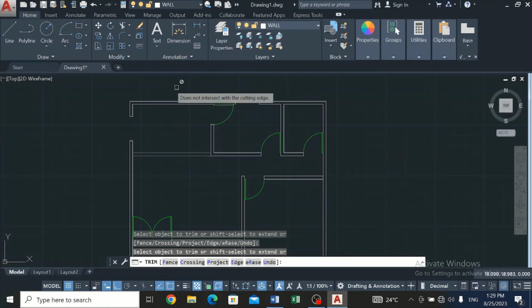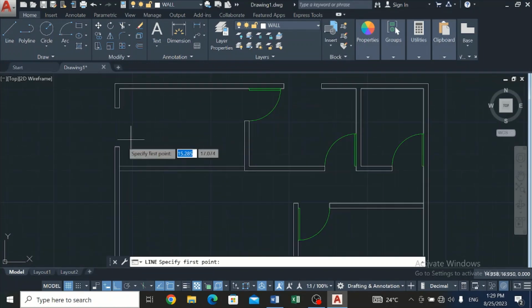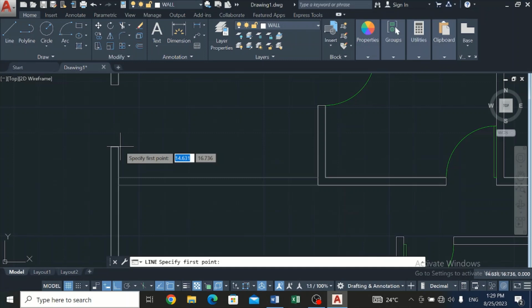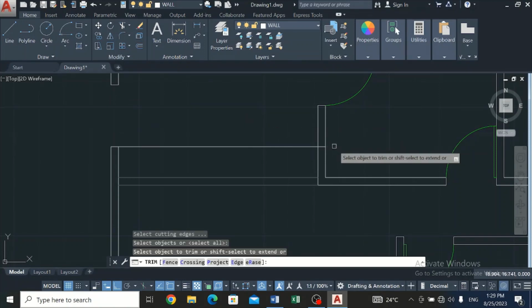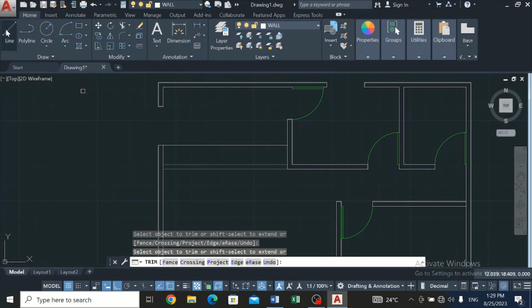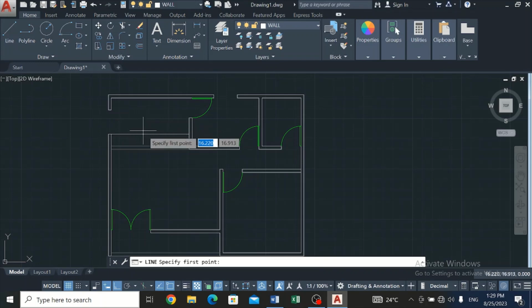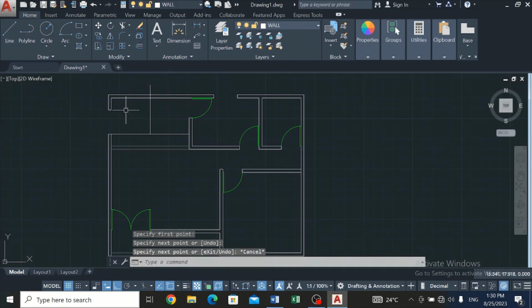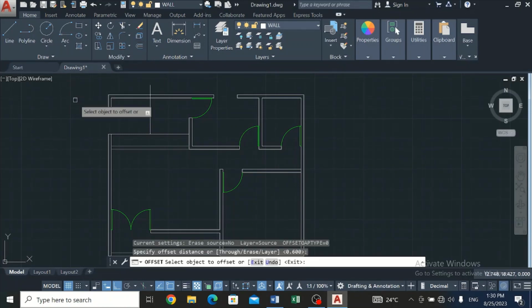I need to create an opening over here, so I'll create a line, drag, hit over here using my trim key, my trim tool. I right click, click on it and this. Now I pick out this line, I click on the line tool again and I move across to get to the midpoint. I drag, I hit the escape button. Now what I need to do is to use the offset, and it's already on 0.6, so I just click on enter,